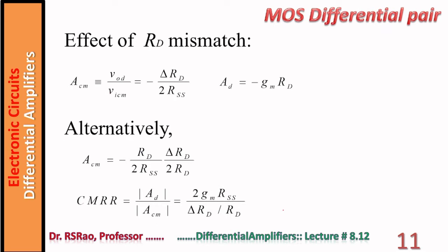Notice the expression derived for differential gain assumes identical stages, but in reality, the story is different. Identical resistors, identical transistors, we cannot have. Even if they are manufactured simultaneously in the same foundry, no two devices can be identical in their behavior.